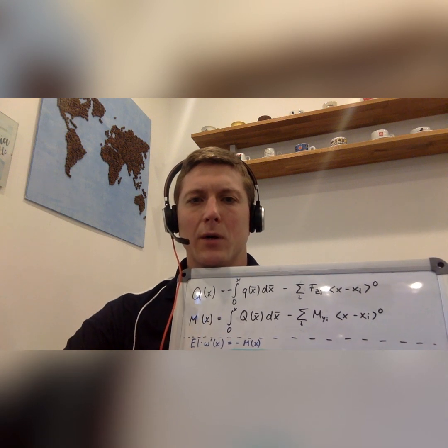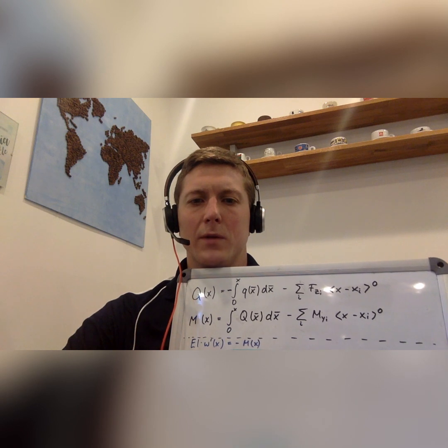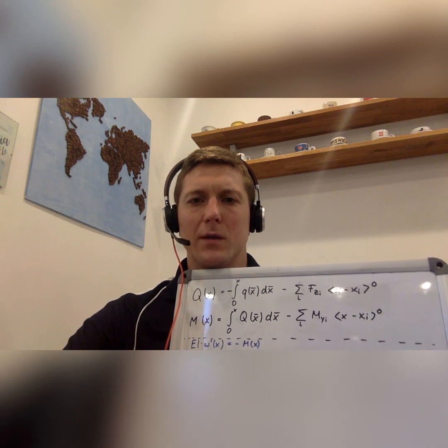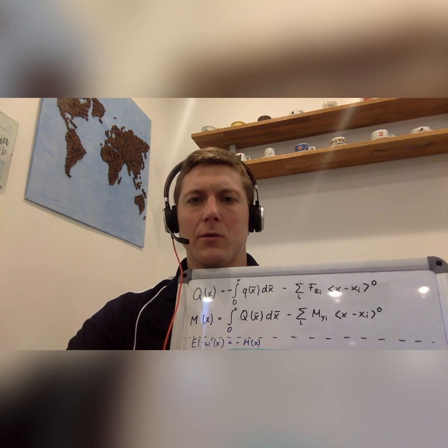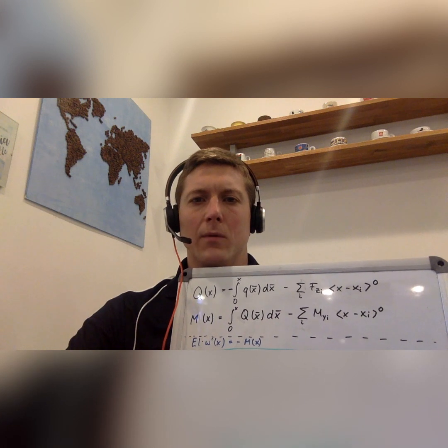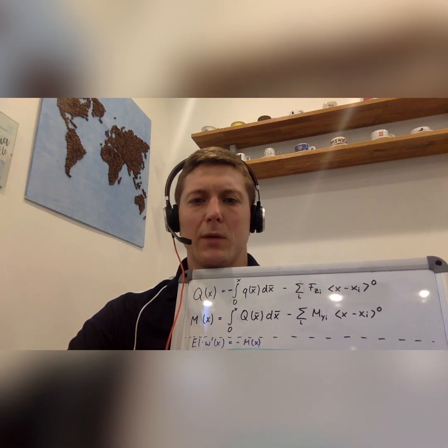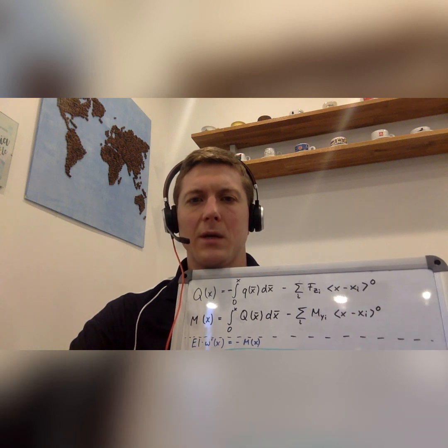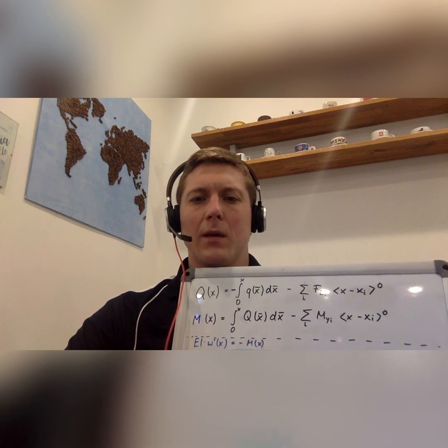In this case, as we are only dealing with planar bodies, so with planar beams, we do not have to consider this I_z, so the area moment of inertia with respect to the z-axis, and we do not have to consider this I_yz, so the area moment of deviation. It would be necessary to include if you were dealing with spatial bodies, and if there is not only a moment with respect to the y-axis but also with respect to the z-axis, then this could be a little bit tricky, but for our course we make it quite simple.